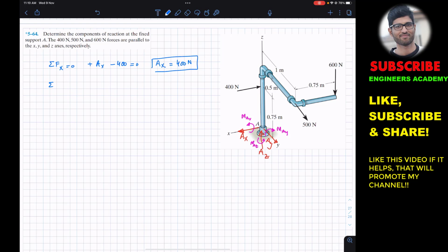Similarly, if we apply the summation of forces along Y equal to 0, in the Y direction we have AY, so we write plus AY, and then we have this 500 Newton force in the positive Y as well, so plus 500, and this is equal to 0.